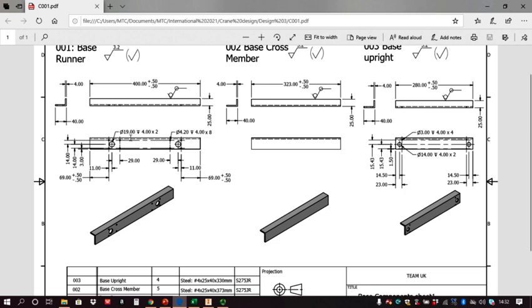And this one, I've actually got that it's a 19mm diameter hole with a depth of 4mm, which tells me it goes through just the sidewall, which is 4mm. I mean, there's nothing else for it to go through, so... But having said that, we could have just been drilling a hole that was only 2mm deep. We don't know, unless we're specific.